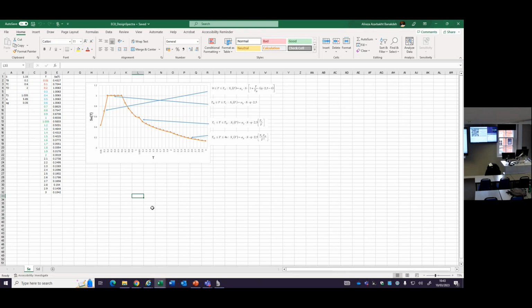Bring your number to the x-axis. Where is it? Okay, it's here. Read the spectral acceleration. This one, as we did today, multiply that spectral acceleration by the mass, and you will get your design force. That's it. This is the whole procedure that Eurocode 8 works by, right? For seismic design.